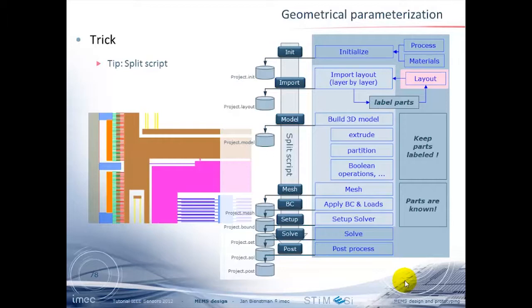And the nice thing is you can develop separate subscripts, and if you are somewhere in a test phase, you apply some more steps, and every time you try it out, it skips the earlier steps, but then it loads the last disk state. So it's incredibly fast. You can just test the last 3 steps and you see, oh, this is a good mesh, or no, I have to change a parameter, or I have to change a dimension. If you do something, of course it has to run. But if it's only on the last steps, gradually you build up the full script, which can be reused in the next project.